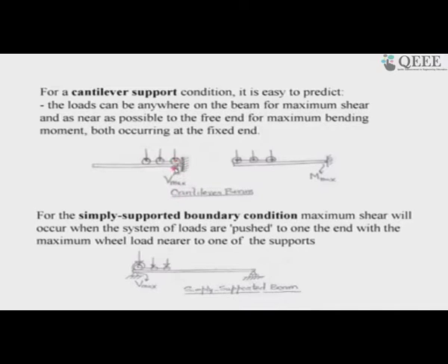Now, it can be the same for different sections if the loads are here. So, it does not matter if I am sitting right past all the loads, and the answer is this. But for the bending moment I want the maximum effect. So, what I need to do is place the loads at the maximum possible locations from the fixed end to have the maximum effect.